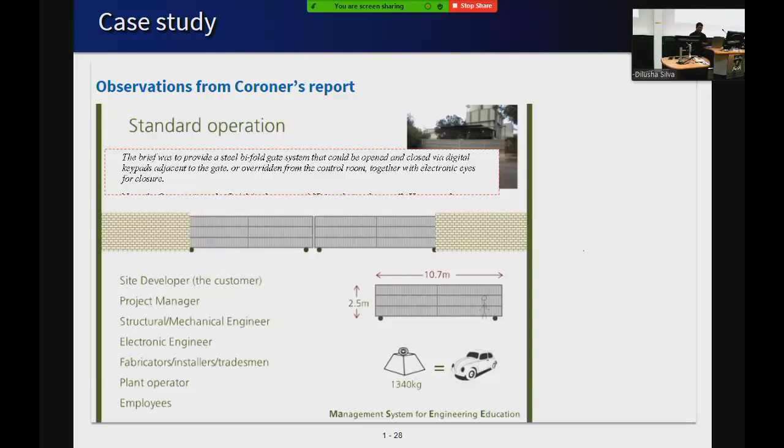With respect to the competence in relation to the gate design and construction, the coroner states, it is relevant to note that neither LEHA or SDA had any previous experience in gate construction or design and are not aware of any particular industry practices in relation to stops. So basically, if that gate had a stop to prevent it going too far and coming off its wheels, it would not have toppled on someone.